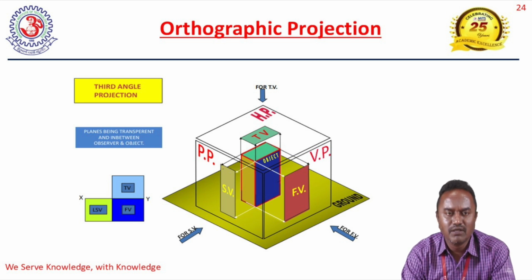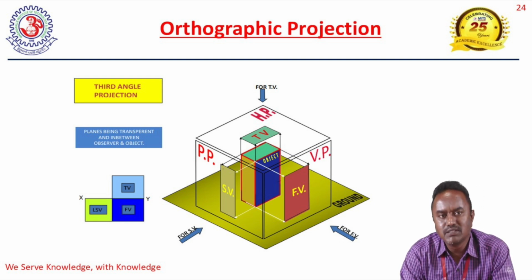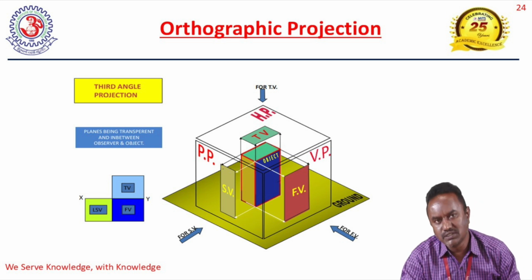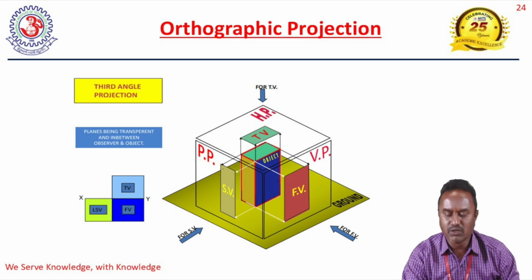In the same way, when any object, it may be a point, line or any solid, is placed in the second quadrant, that is called a second angle projection. So we can describe the second quadrant as above HP, behind VP. The same way, third quadrant is below HP, behind VP. So it is just a reverse of the first quadrant. Then fourth quadrant is below HP, in front of VP. So these are the four quadrants. We can place the objects in four quadrants, then we can get the different front views as well as top views.